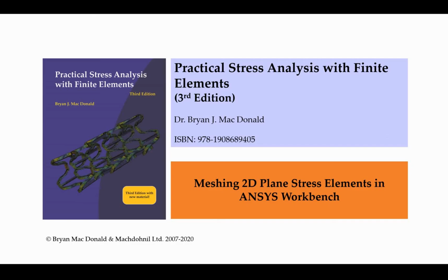In this tutorial we're going to be basing it off a case study from this book, Practical Stress Analysis with Finite Elements by Brian J. MacDonald. And we're going to be looking in particular at meshing 2D plane stress elements and how we'll do this in Workbench, how we can control the mesh and control the type of element that's used.